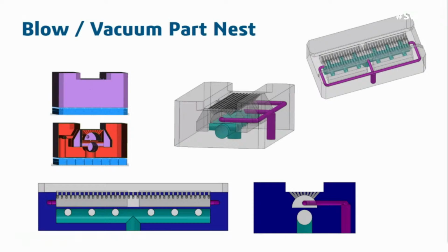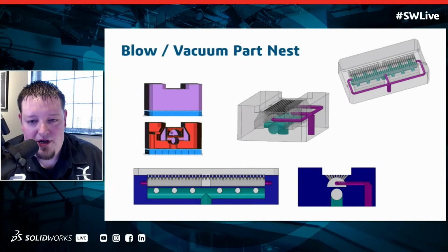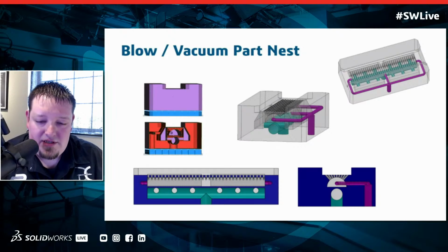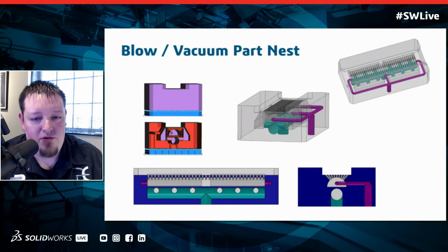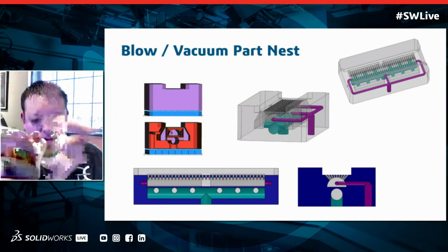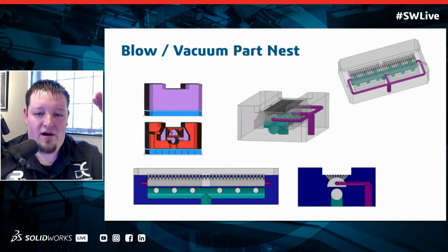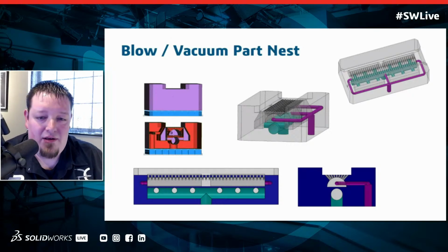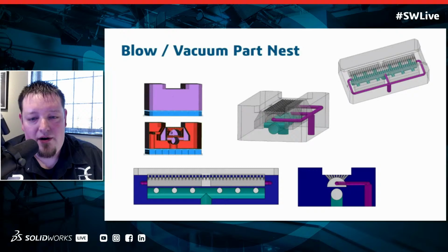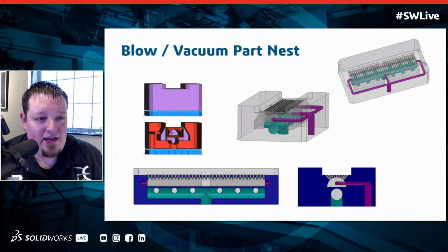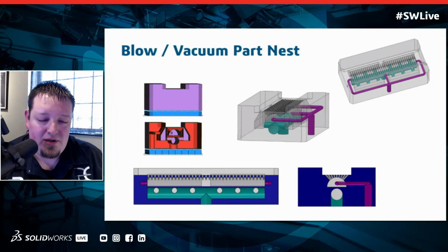Yeah, so if you look at the left-hand side of the slide here, there's that red section cut through the middle of the detail. And you'll notice that in the center, we have an arch, and that is our pressure chamber. That's where we're blowing air through that array of holes across the top of it. And then off to the sides, you'll see there are some 45, or actually probably more like 60-degree angles going up to our vacuum mouths. And those are vacuum chambers. And so an arch is a self-supporting structure. So think about bridges back in the Roman days, right? They always did them as an arch because it was self-supporting. Same thing here. You don't have to print supports inside of there.